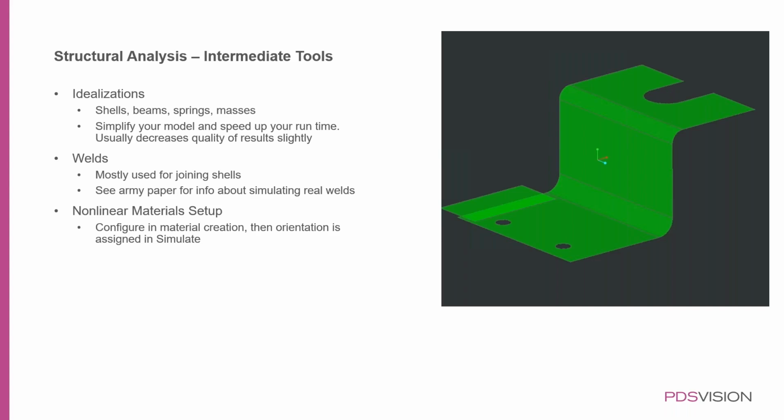For example, if I want to mesh the structure, or I want to determine the structural characteristics of a car body, I'm not really going to be concerned with the specific build of the engine. So oftentimes what people do, if they're just trying to simulate the car body, is replace the engine with a mass. Basically, we're saying we don't care about the geometry of that engine, but the mass it has is still important to us. So all those are going to simplify our geometry. They're all going to make our simulations run much faster.